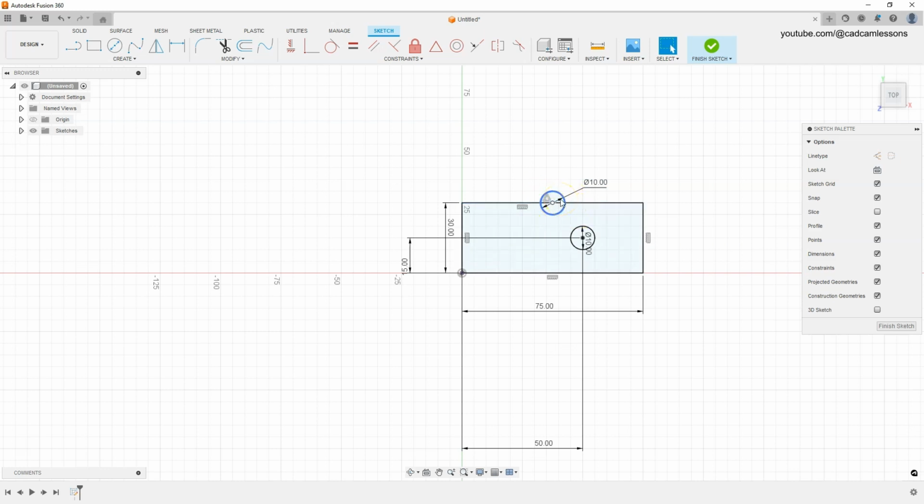And that's the advantage of constraints. By using constraints, we can be a little independent of the dimensions of the geometry. If, for example, we want some geometry to be placed in the middle of another geometry, then a better solution may be to use constraints rather than using dimensions. Then, regardless of what the dimensions of the geometry will be, this geometry, which is to lie in the middle of the selected side, will always lie in the right place.